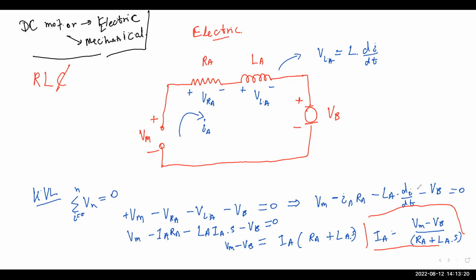Okay, so we have one equation now of a model. We have a model for our current, right? Now we also know from our theory that the torque of the motor, if we assume it's Tm, is proportional to the armature current, the current that we obtained earlier. Now we can assume the proportionality constant is, say, Kt, and we can get Tm equals Kt Ia.